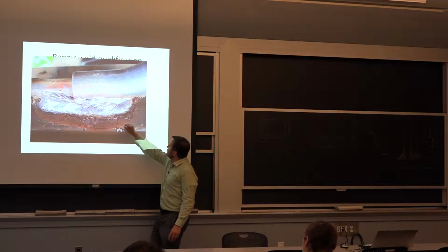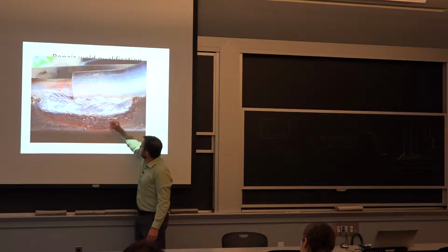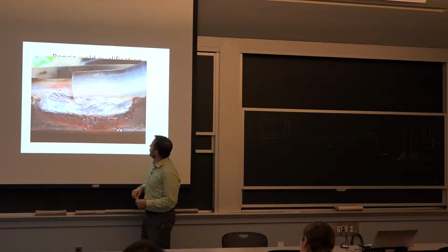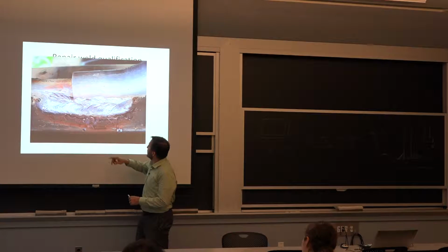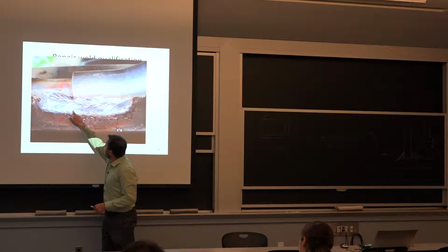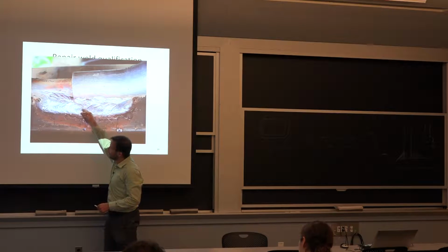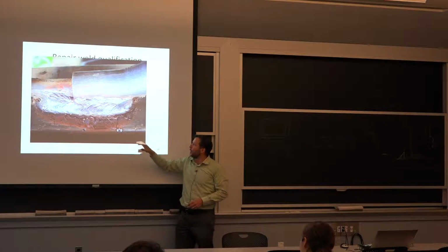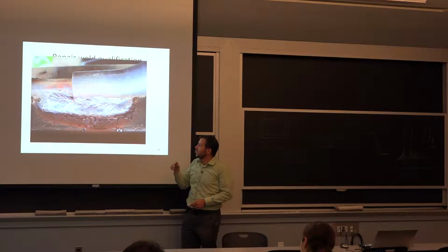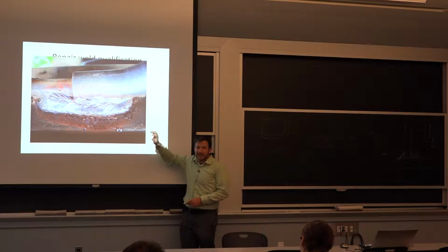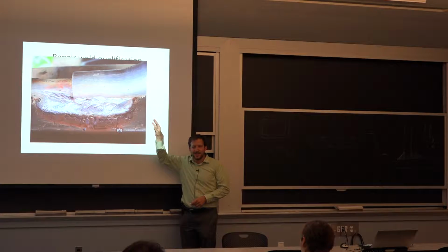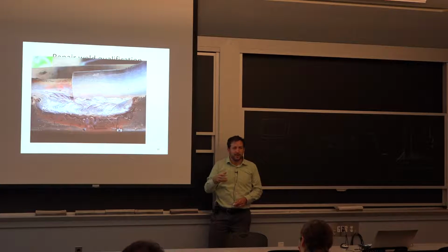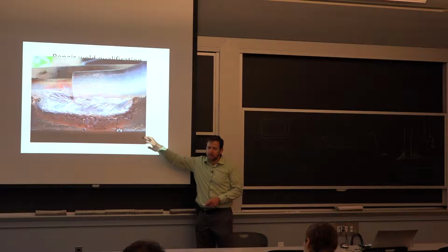So essentially, we see the evolution of the melted pool as we were moving forward. It's going this way. At every point in time, the fusion zone starts to solidify and leaves you a mark behind. I brought in this image just to emphasize that this is not a problem. Okay, the idea that there's a little bit of a surface profile on the weld, a lot of times is actually a good sign.